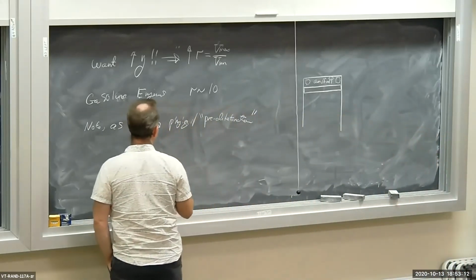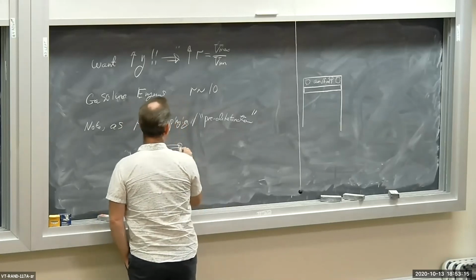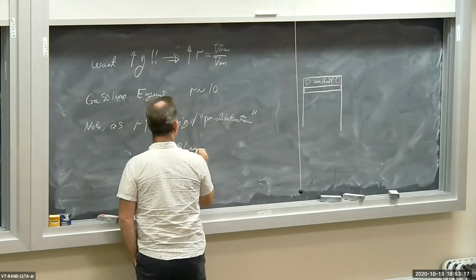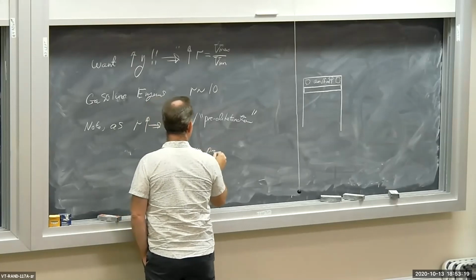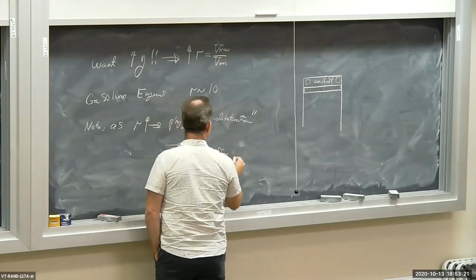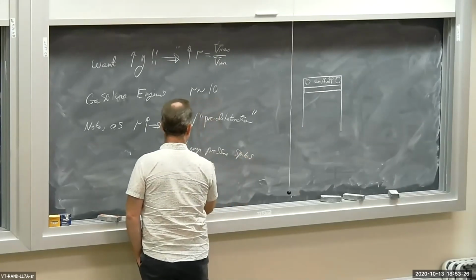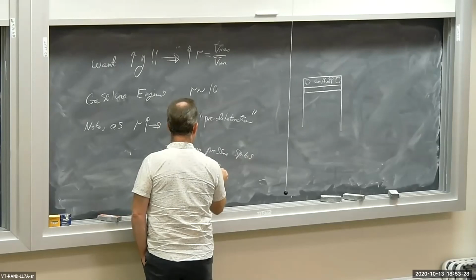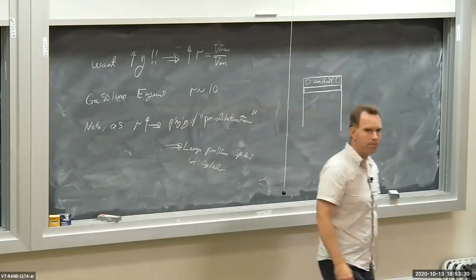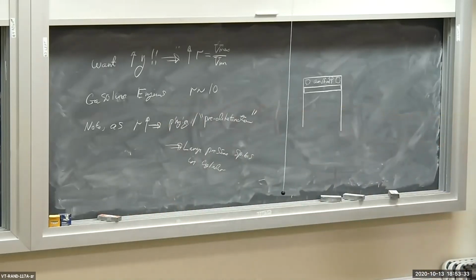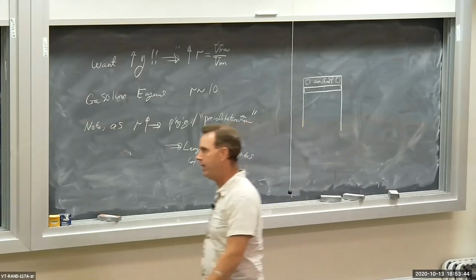So if you get pinging and pre-detonation, you get large pressure spikes in the cylinder. And those pressure spikes, actually you can hear them, called pinging. The engine will make a ringing sound or a knocking sound. So you get large pressure spikes in the cylinder, and that will do damage to the engine, mechanical damage.